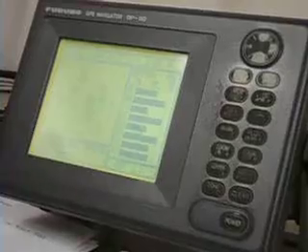Now where do we find out which is good or not? For this machine in 2D mode, dilution of precision should be less than 3. In 3D mode, 3-dimension mode, dilution of precision should be less than 6. It is given here.